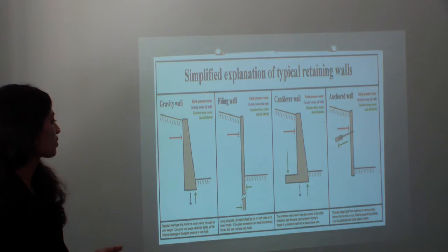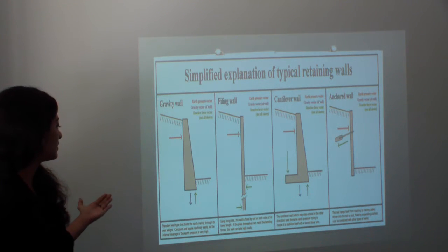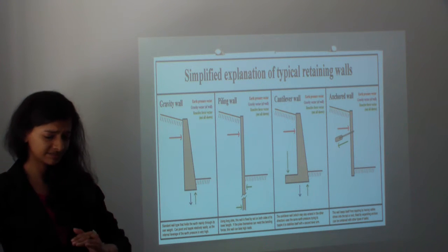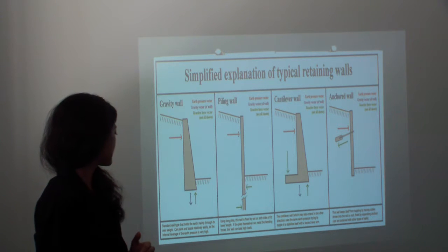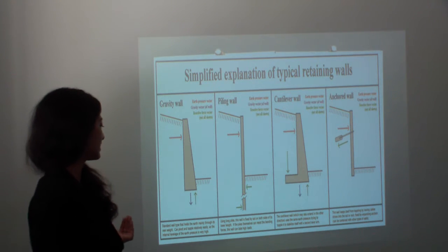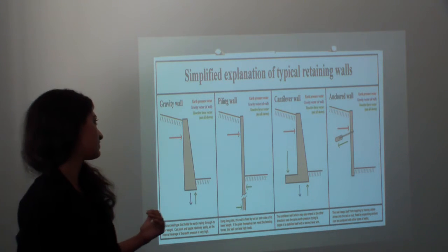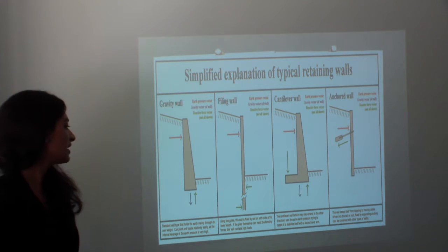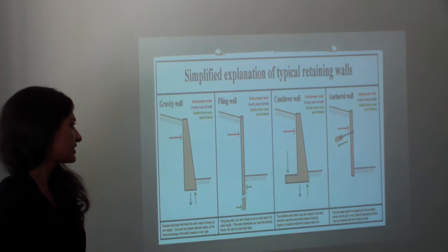And a quick survey of the types of retaining wall. These are the pictures showing the retaining walls. It's gravity retaining wall. It mainly withstands by its own weight, and relatively easily, and internal leverage of earth pressure is very high. Earth pressure is very high in the gravity wall. And about the piling wall, its piles themselves can resist the bending of the retaining wall.